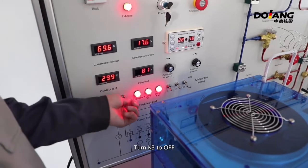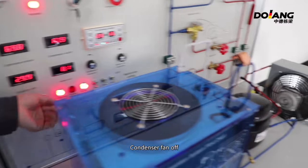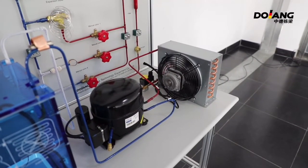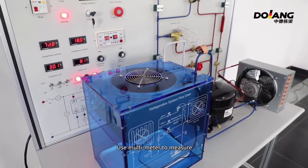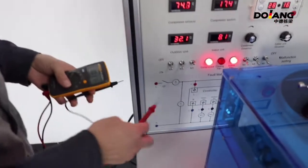Now do the third fault experiment. Turn K3 to off. Condenser fan off. Use a multimeter to measure. Turn the multimeter to the AC voltage gear.